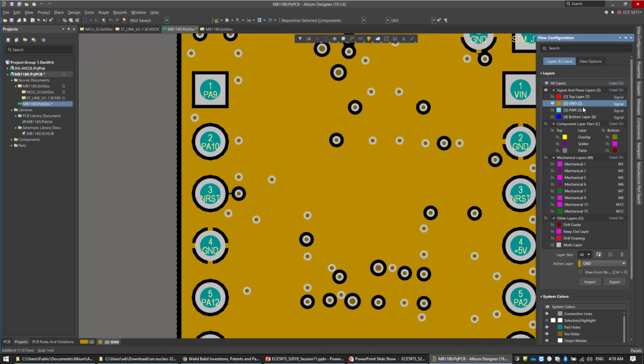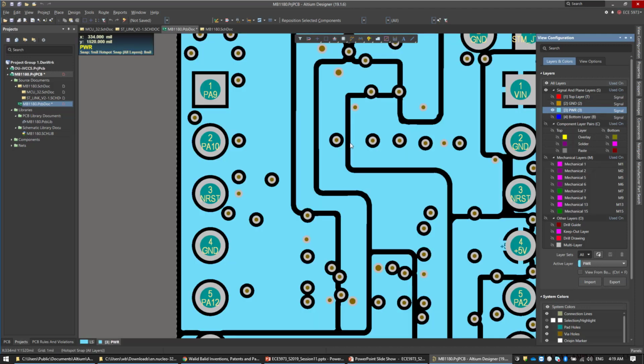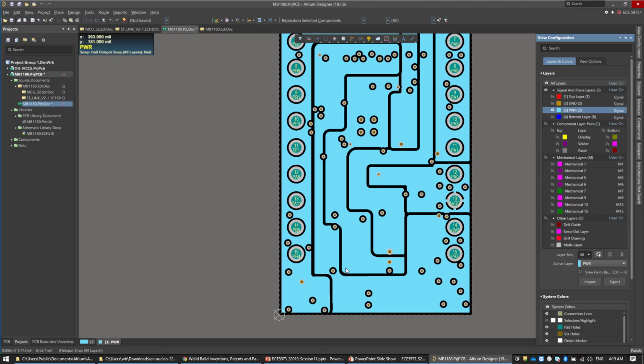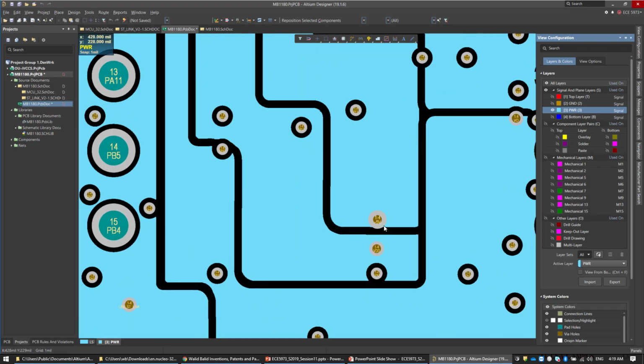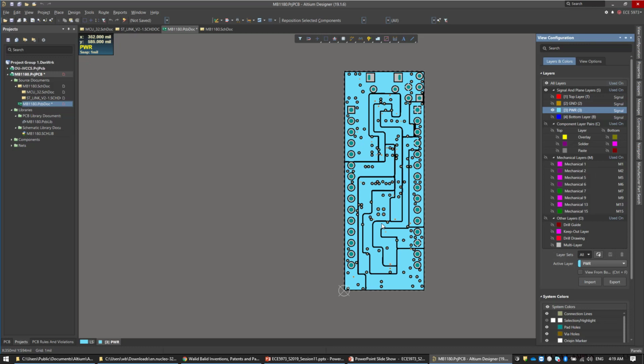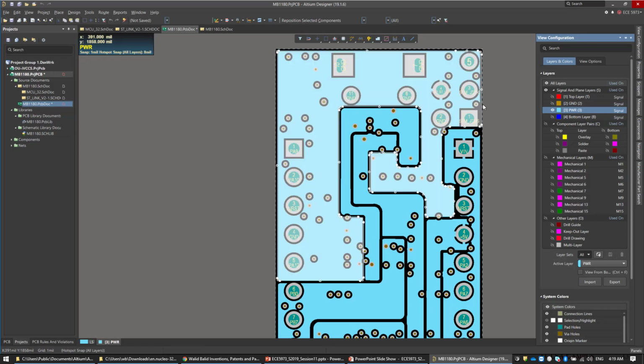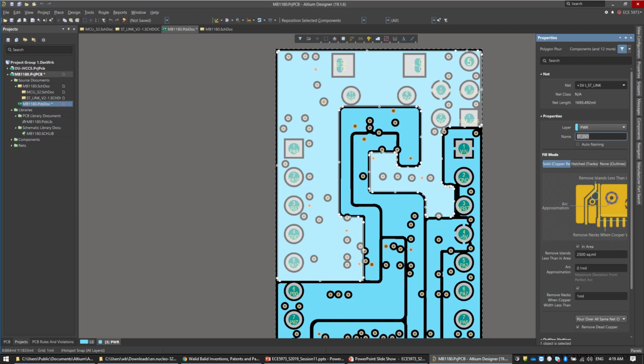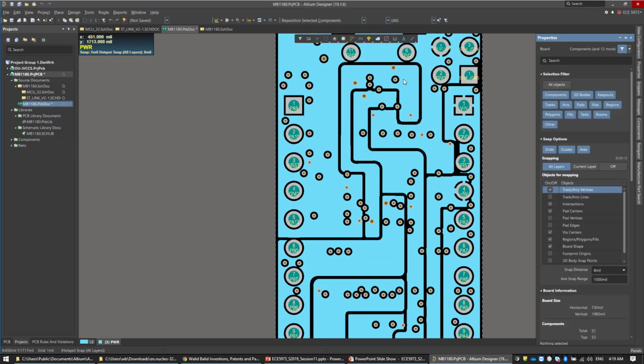And if you come closer, look at these vias, they are connected to the ground and they have a power signal. And look how they did, and this is a new design, by the way. They have sections. So this section is basically, let's click on it to see what this is about. This is 3.3 volt ST-Link. This is the power supply for the debugger and programmer.